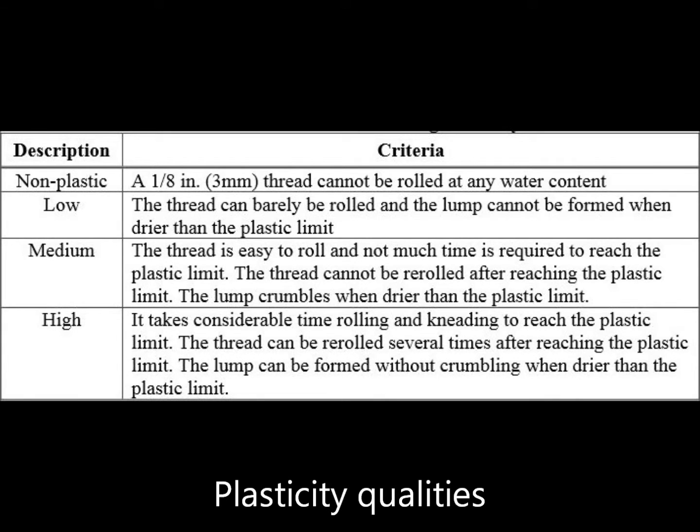Plasticity. In the plasticity test, we noted how long it took for the process of rolling the soil into a rope to result in the soil crumbling. The longer this process was, therefore, the higher we can say that the soil's plastic limit is, which is characteristic of clay, whereas silt would have had a lower plastic limit.